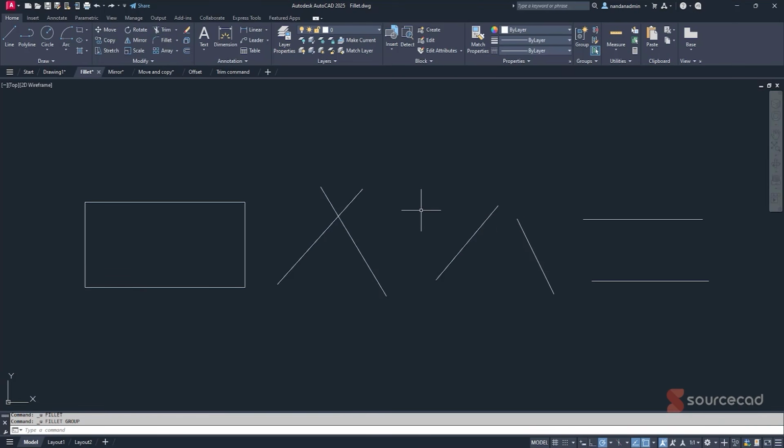Okay, let's look at the next example of fillet command. So I'll select fillet here. And what if we want to add fillet on all the 4 vertices? Well, for that we have a direct method. I'll go to radius and first I'll select the radius of, let's say, 0.5 unit this time. Press enter. And now I'll select this polyline option. As this one is made with a polyline, which is the connected curves, it will work here in this case. So I'll go to polyline, I'll select on any of these lines and we have fillet on all the 4 vertices. That's it.